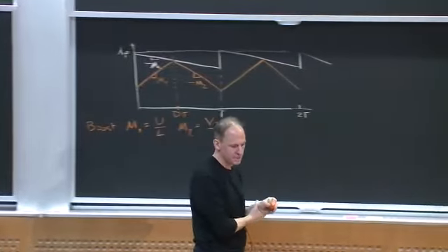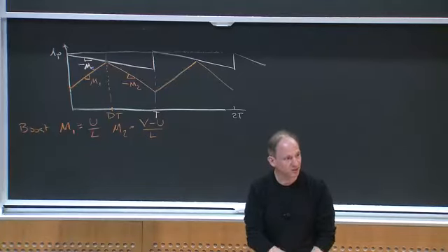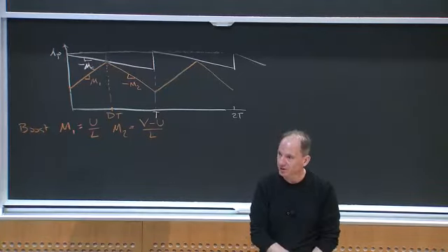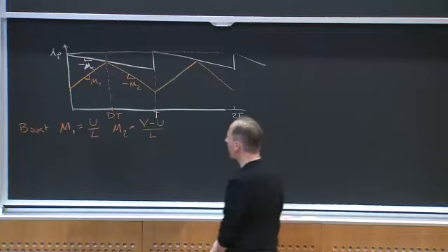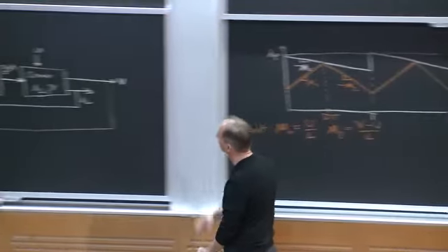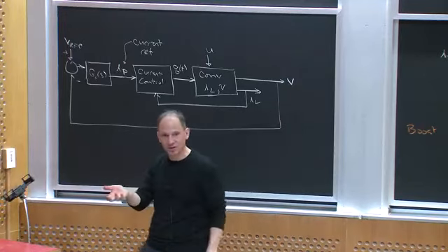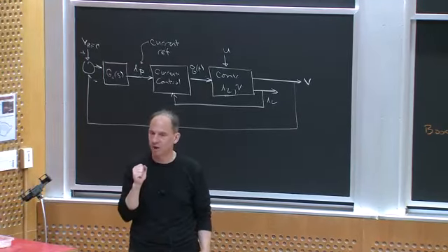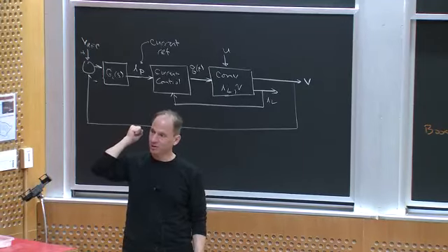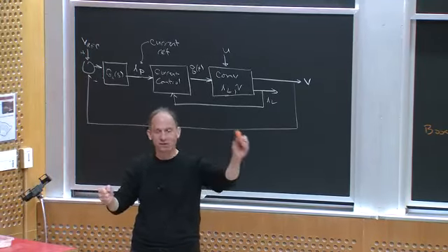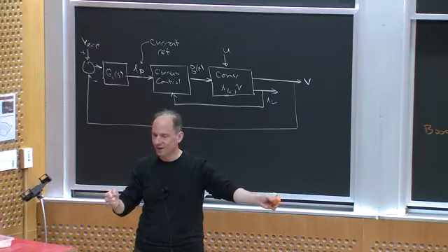Okay. All right, so one thing it gives us is this cycle-by-cycle current limiting. The other thing it's going to give us is better dynamics, okay? The question is, how do we analyze the dynamics of this thing? What did I do before? The thing I did before was we averaged the circuit, or the state space model, and came up with a duty ratio, and then we linearized it, and we came up with a conversion between the duty ratio and the local average inductor current and local average output voltage, right?